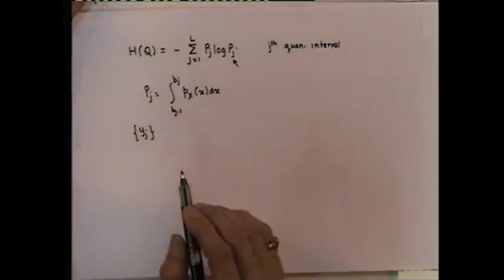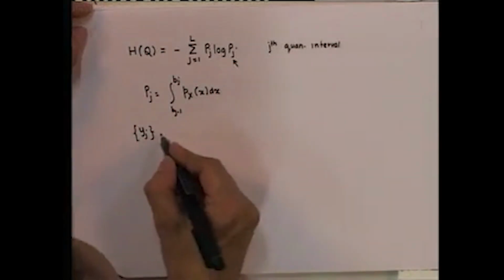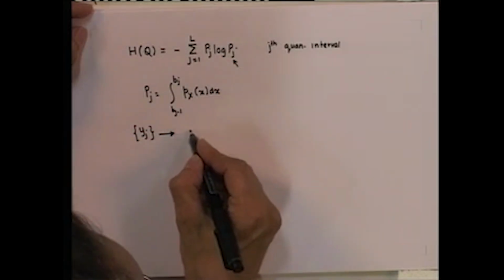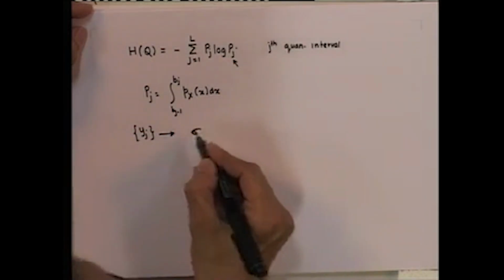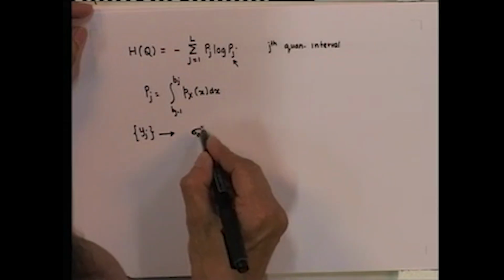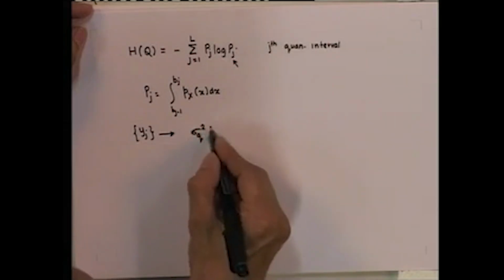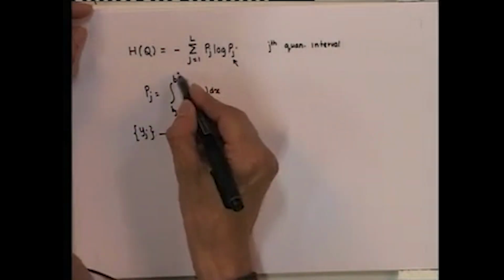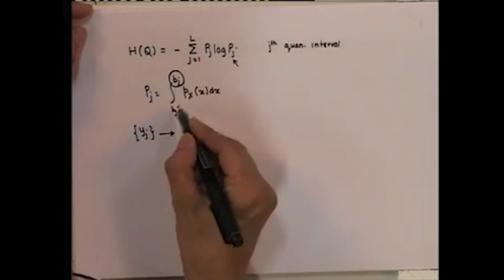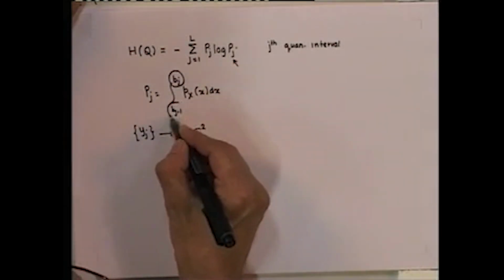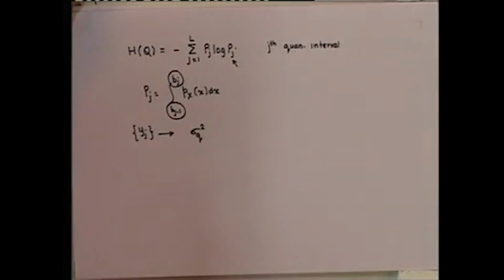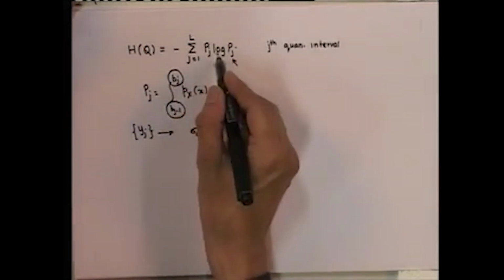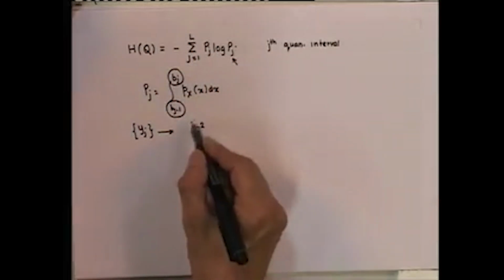So, what this implies is that y j can be selected solely to minimize the distortion, that is the mean squared quantization error. However, the selection of the decision boundaries does affect both the rate and the distortion.